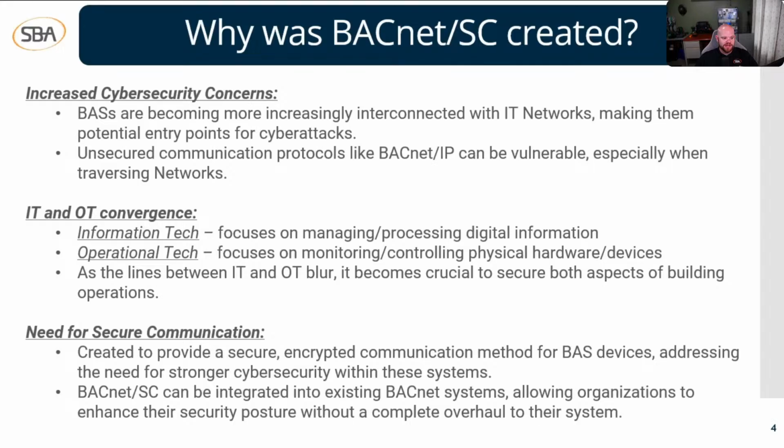And then the issue here is that as we move along in the future, more and more of our BAS controllers are turning into IT assets. So this last point here is basically stating that. As we go down the line, IT and OT work closer together. So the line starts to blur there, and when that line blurs between IT and OT, it becomes crucial that we make sure that we're securing both aspects of our building operations. So that's on the IT side and the operational side as well, so the OT side.